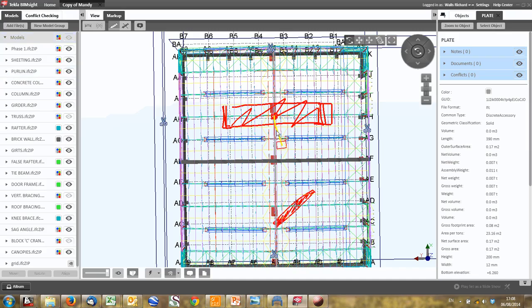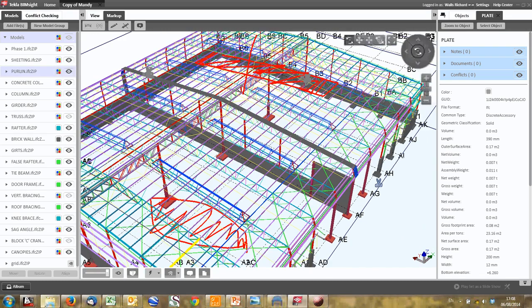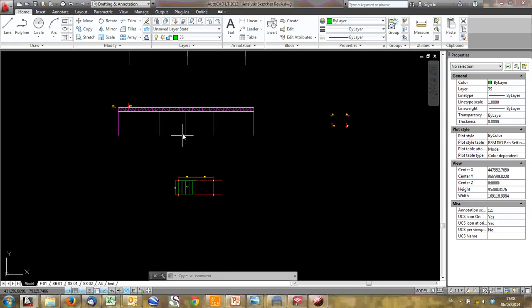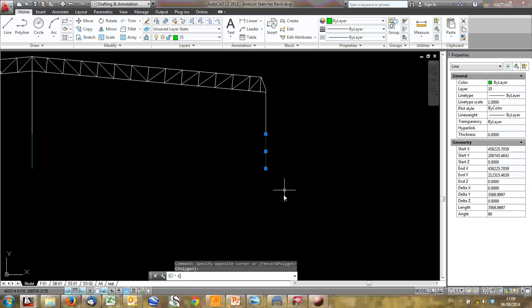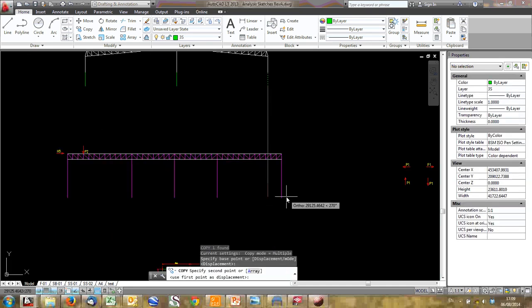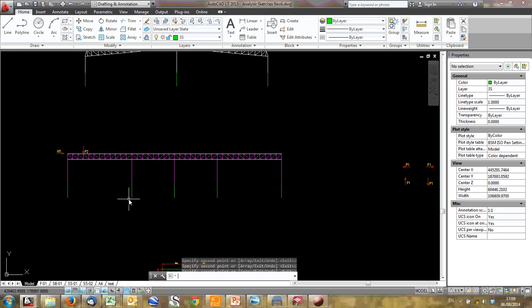Right, but now we've actually just gone through an entire warehouse from start to finish in terms of steelwork. You can then size your girder, size your columns. You can get your reactions from your steel columns and size your concrete columns. So you'd get a force here. I should actually draw these bottom ones in green to show that they're concrete. Let me just do that quickly. So you have your concrete columns at the bottom, where the bottom of this column is where your steel is.